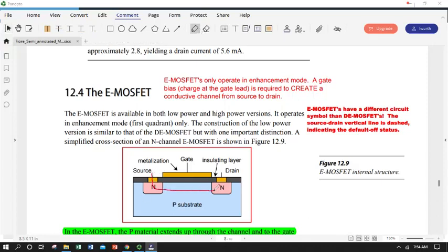This current can't flow. No current. Because if we forward bias this junction, we reverse bias that. So that's basically back to the dilemma of how does a BJT work. This is not a BJT. So we're not going to run current through the gate, certainly, because it's an insulator. We can't do that at all. We'd ruin our device. So we're going to do something totally different.